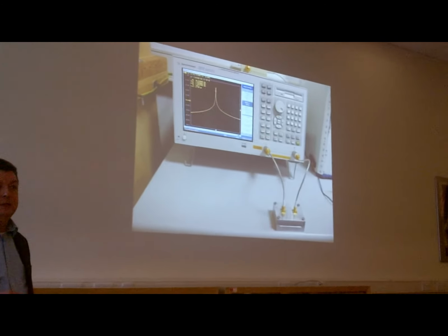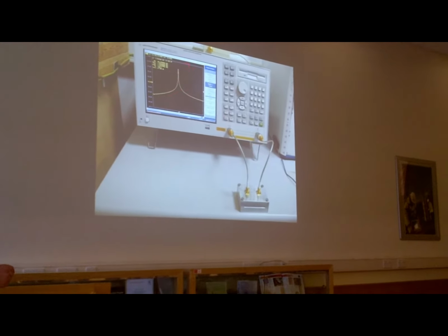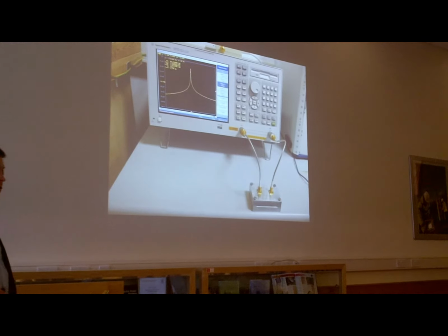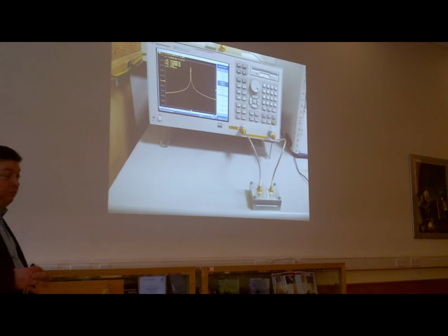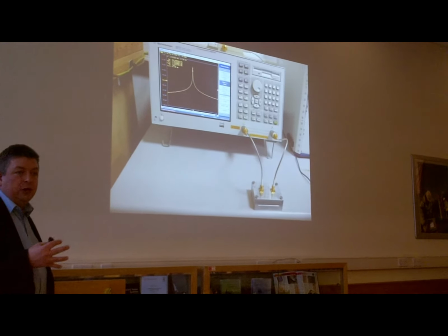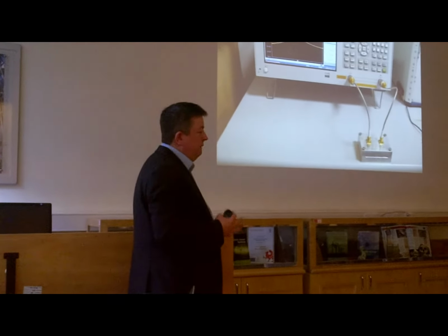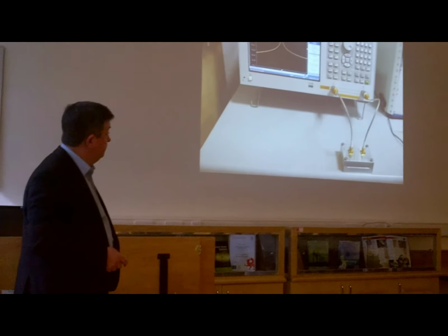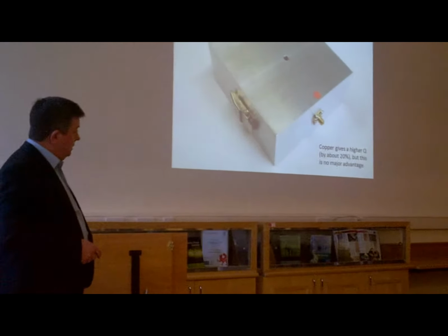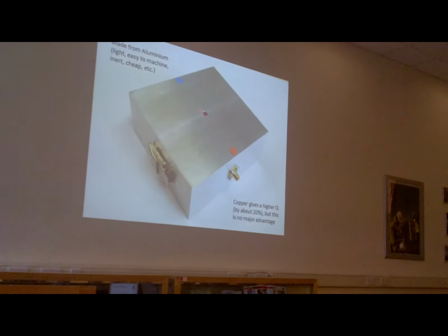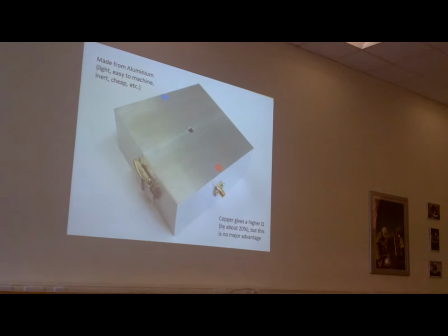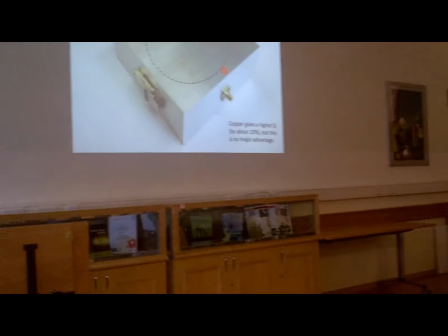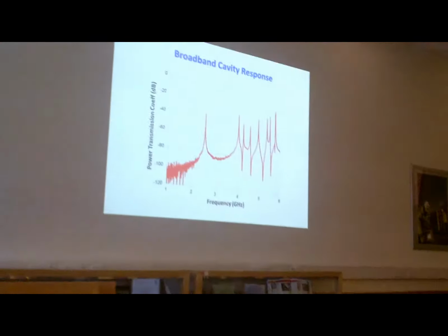And what we see here is a nice classical frequency response to the resonance that these network analyzers give you. And you can measure that to an accuracy of about 10 Hz at about 10 gigahertz. So you have frequency resolution of the order of 1 in 10 to the 9, and hence you can measure very, very tiny changes in material properties. So you can track with exquisite accuracy, really, fundamental changes like chemical reactions, change in phase, anything of that nature.